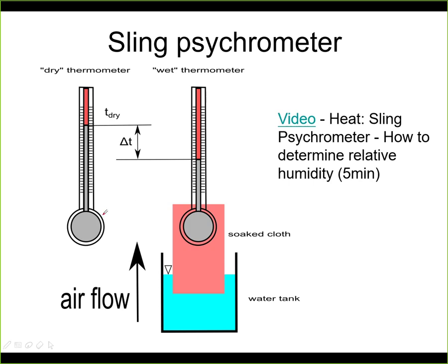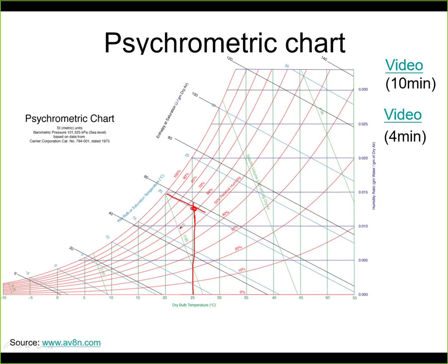Some have thermistors, for example. Some may have PT100s, but it's mostly thermistors because of the price, and we don't need such a high level of accuracy for the temperature. If we calibrate the sensors properly, here it may be sufficient to have a resolution of, let's say, 0.5 centigrades approximately. This is not a very precision device. You may measure with it within a few percent of relative humidity. So let's say plus minus 3, plus minus 5, which is usually sufficient.